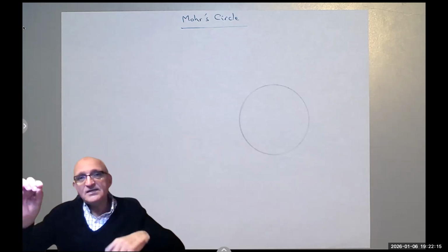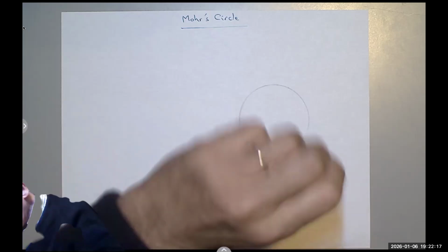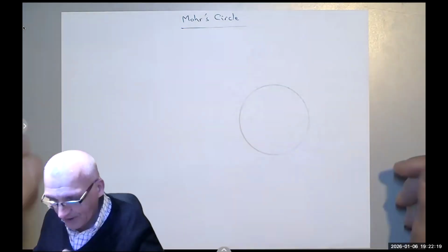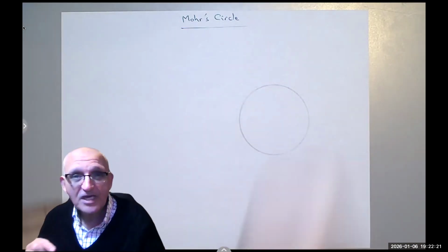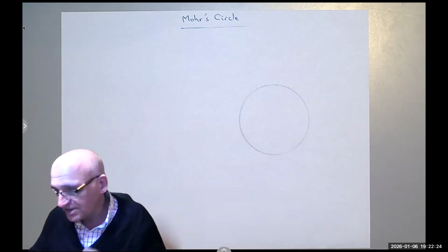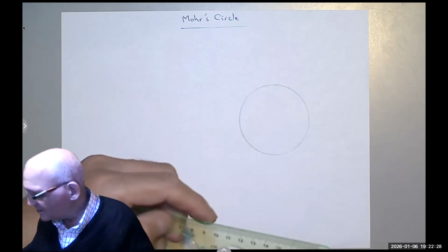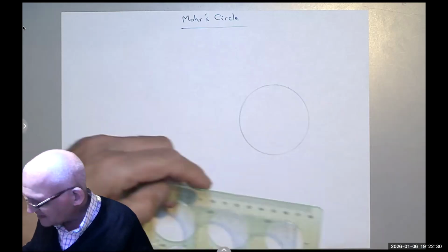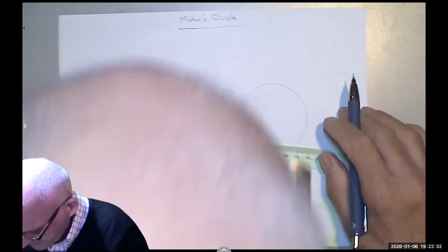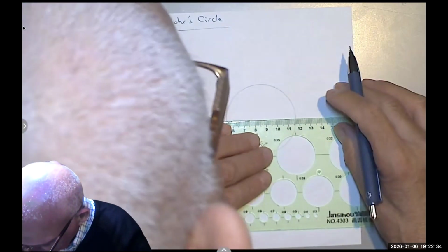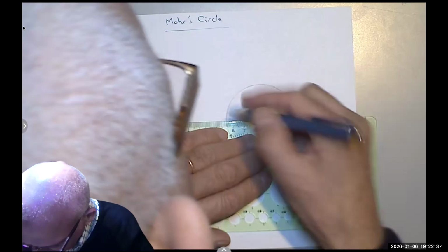Okay, so every element, if I take a piece of element from a body, based on its location, I can find the normal stresses that I will draw the Mohr circle and use the x-axis of it as my sigma, or the normal stress. So the normal stress would be calculated here.